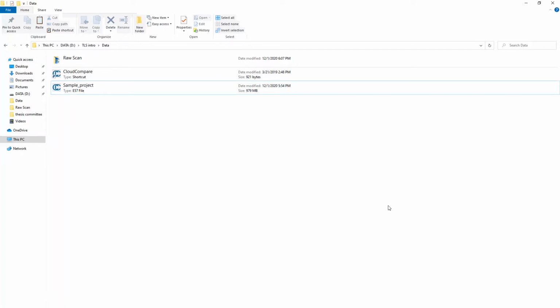Since converting the data format is relatively easy to do in Autodesk Recap, I will skip this step in this video. And here is already a scan from a former project. It has already been transferred into E57 format. Next, we can use CloudCompare to visualize the scan and do some basic measurement. CloudCompare is an open source software and it's very powerful. Now we can open the data.